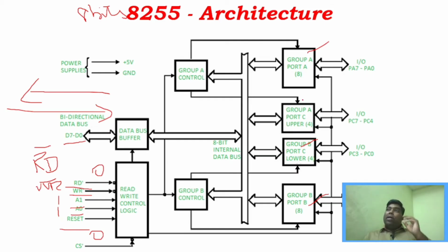But the modes of operation of these ports, whether it is working in mode 1, mode 2 or mode 0, will be determined by the control word register. So how will the control word register be configured? The control word register can be configured through the pins D0 to D7. Based upon this configuration, it will make these ports work in different modes of operation. We will see in depth about these modes of operation and configuration in the next video.